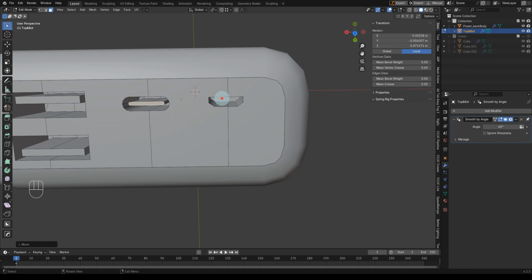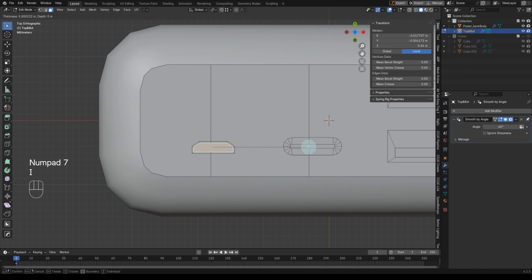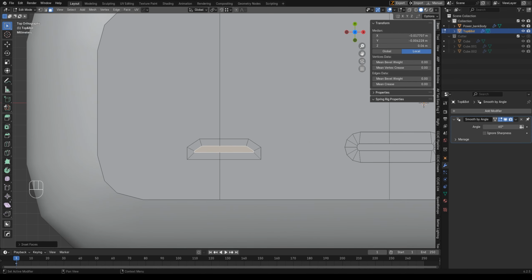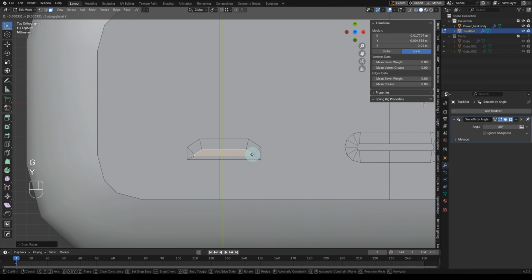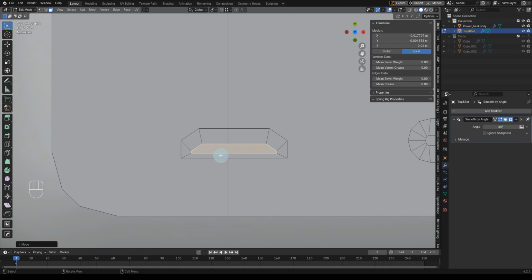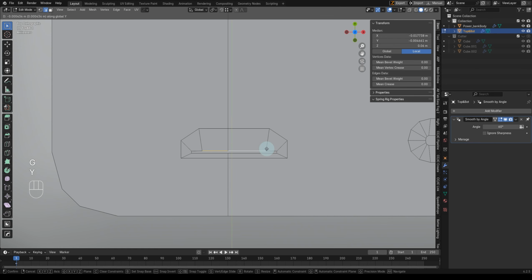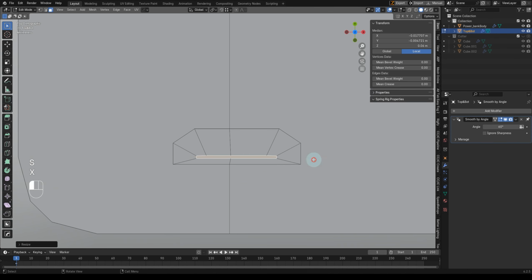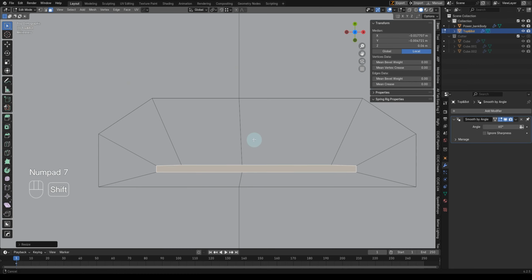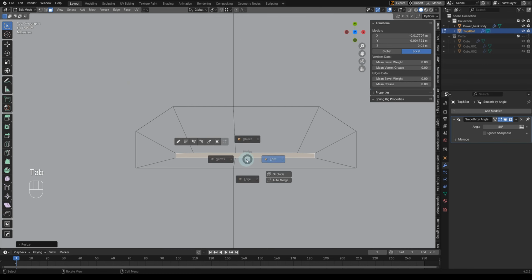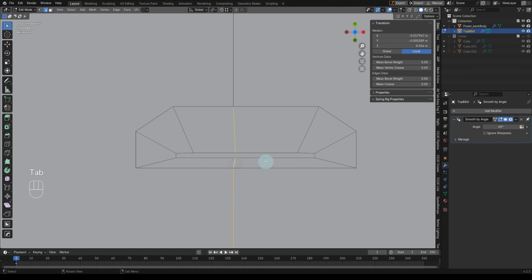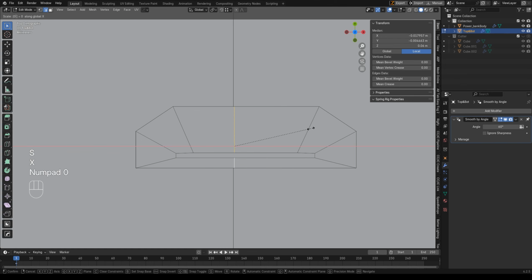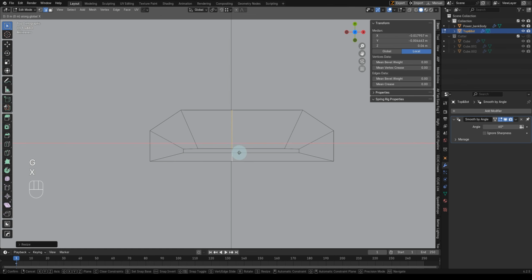Okay, so for this, in face selection mode, let's press I to insert to somewhere around here. But I see now, I'm thinking, okay, let's switch to a selection mode and then move this one around here. Nice. In face selection mode, select this face and S and X because it's this small. You may see I'm having some distortion here. Go to face selection mode, select both of them like this. And then I press S and X 0. Nice.